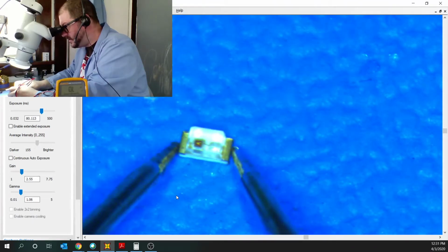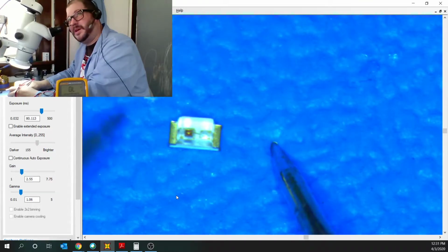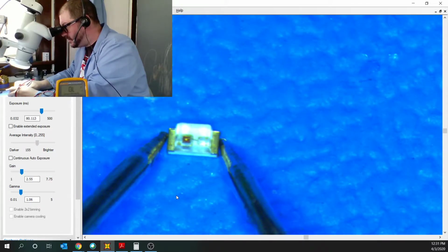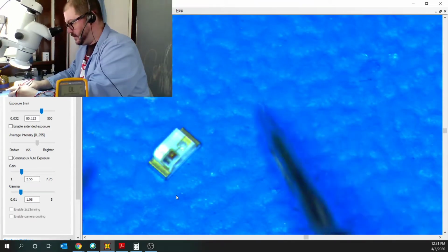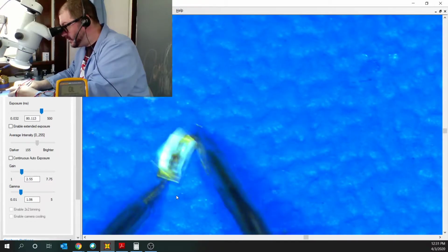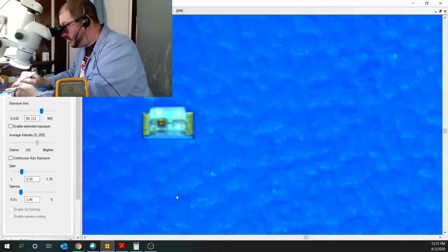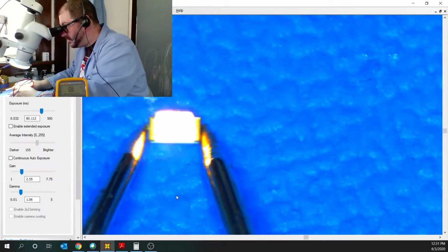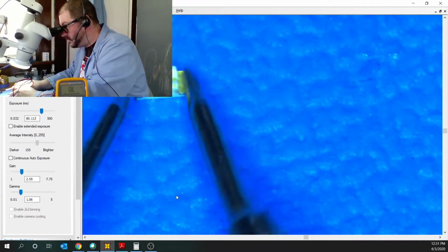So when I touch the 2 ends with the red on my right hand, this is my red and this is my black, that is the incorrect way. Notice that the multimeter probably says OL or something close to that in this configuration. But if I switch my probes around so the red is on the left and the black is on the right, oops, sorry, hard to hold these into place while doing this.